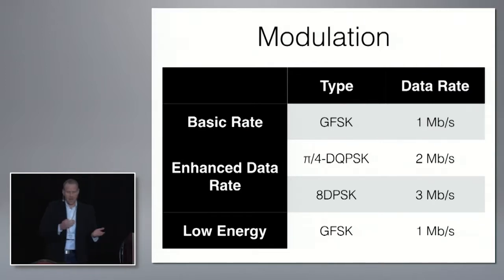So as a result of that, per the specification, because it's a non-Wi-Fi device, it needs to be 20 dB above the lowest modulation coding sensitivity, which is negative 82 according to the specification. So that means any Wi-Fi device that hears a Bluetooth device at greater than negative 62, the energy detect will trip, and it's going to go to a medium busy, which will hold off.